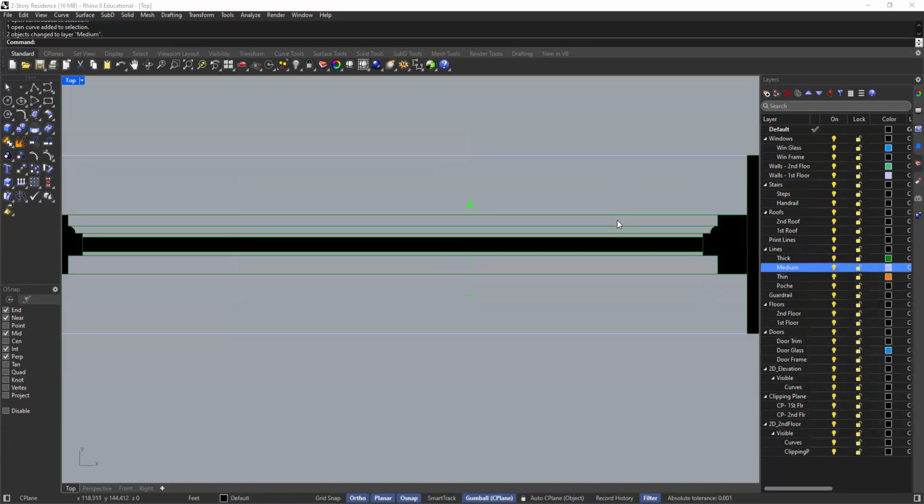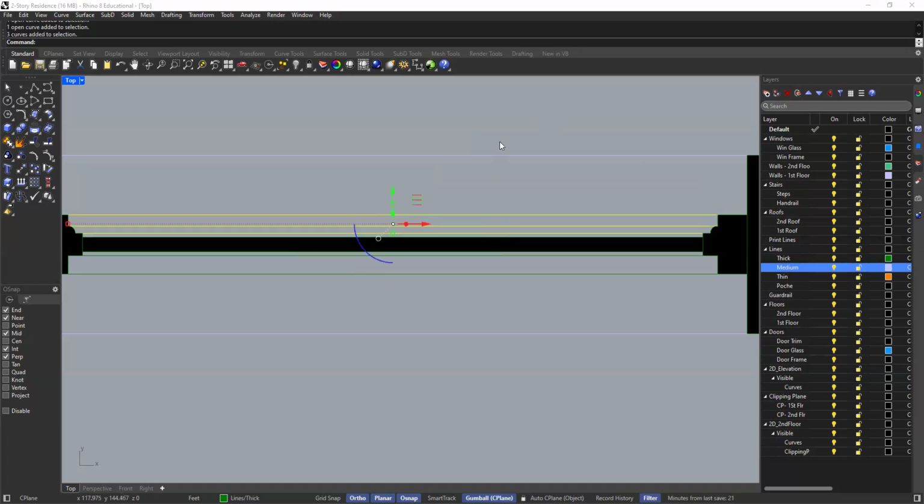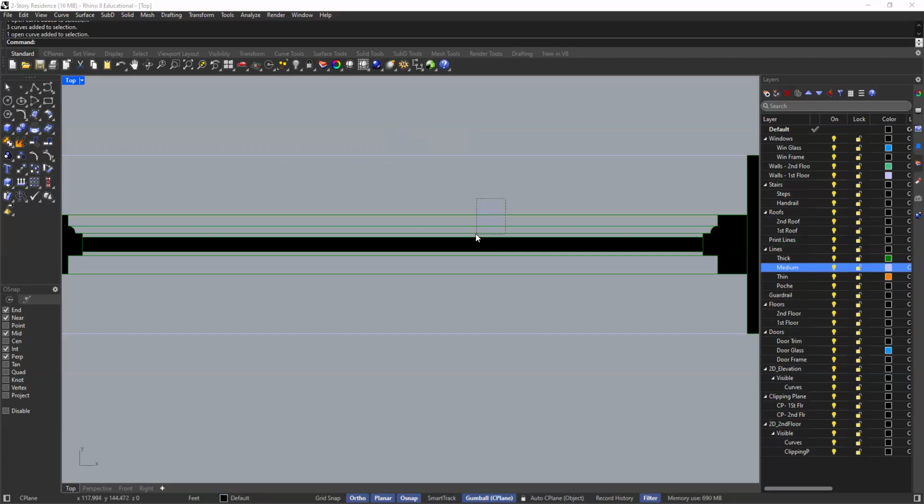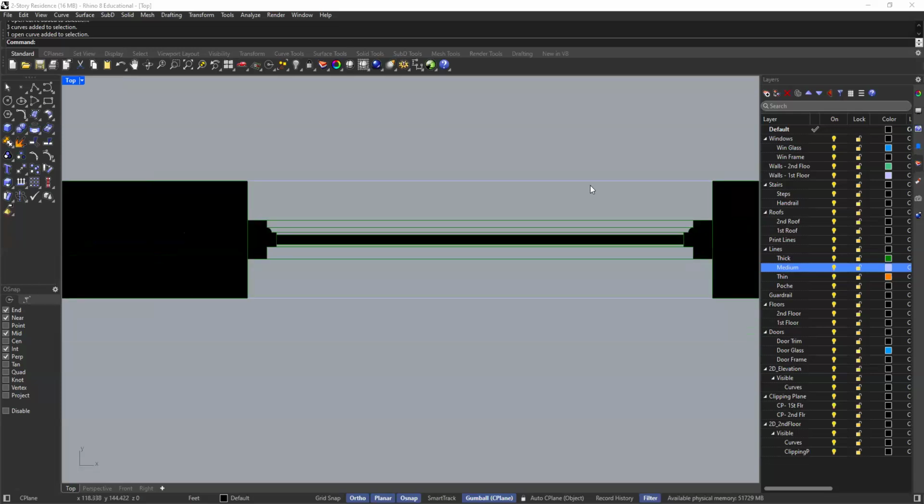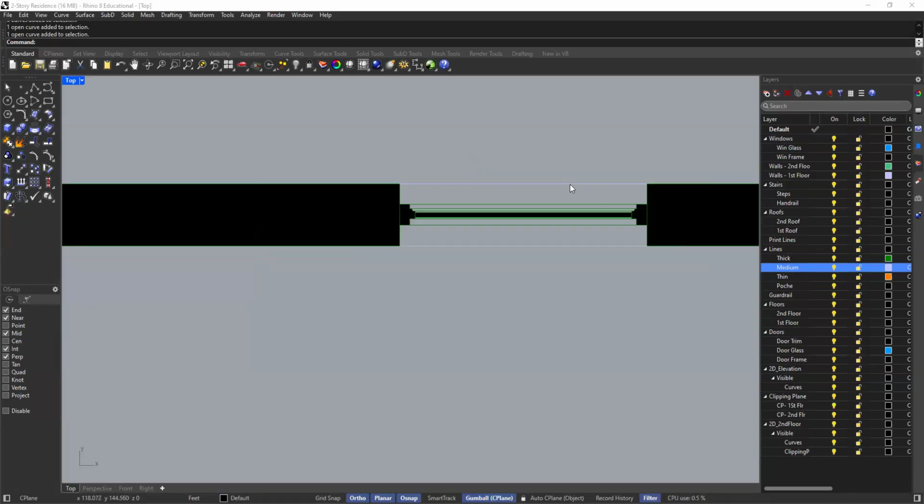Okay. Now, technically, these lines are closer to us, right? So technically, if we're following this logic that the line work that's closer to us should be thicker and the things that are farther should be thinner, technically this should be thicker than this because these lines are actually closer to us than this line. These lines represent the frame. This represents the sill. All right.